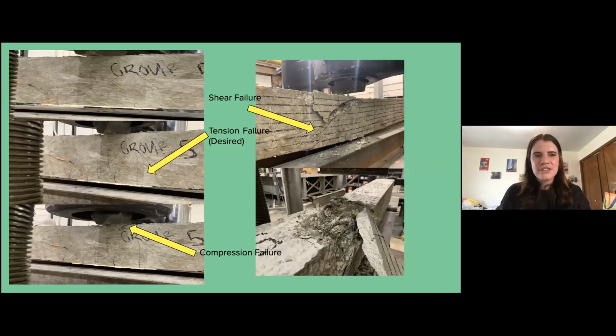If you imagine that you have this beam inside of a room, inside of a building, you want to see those cracks forming underneath first. And that's a good sign. It shows that it's failing exactly where it needs to. You can see those cracks. Your beam will still hold, but it is showing cracks in the concrete itself, but your steel is still holding on to it. But eventually, after we did add enough load on the bottom, you can see it did fail